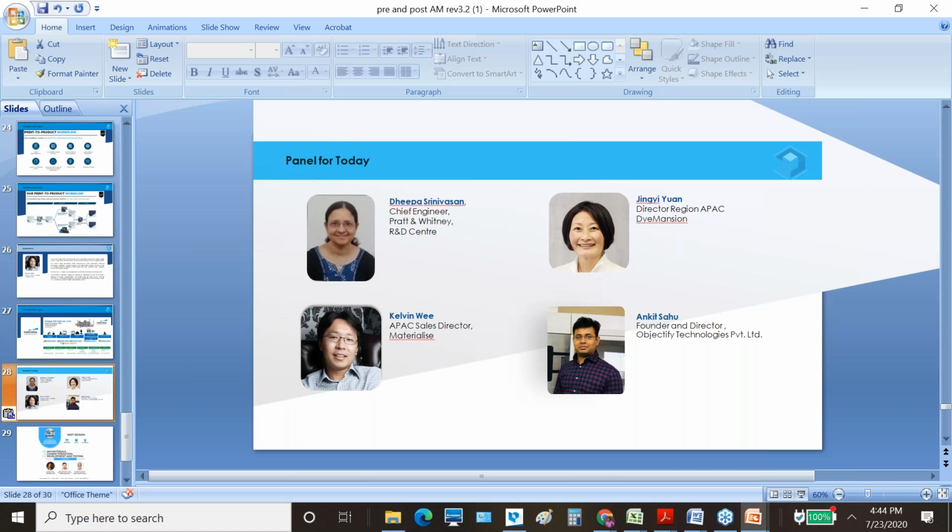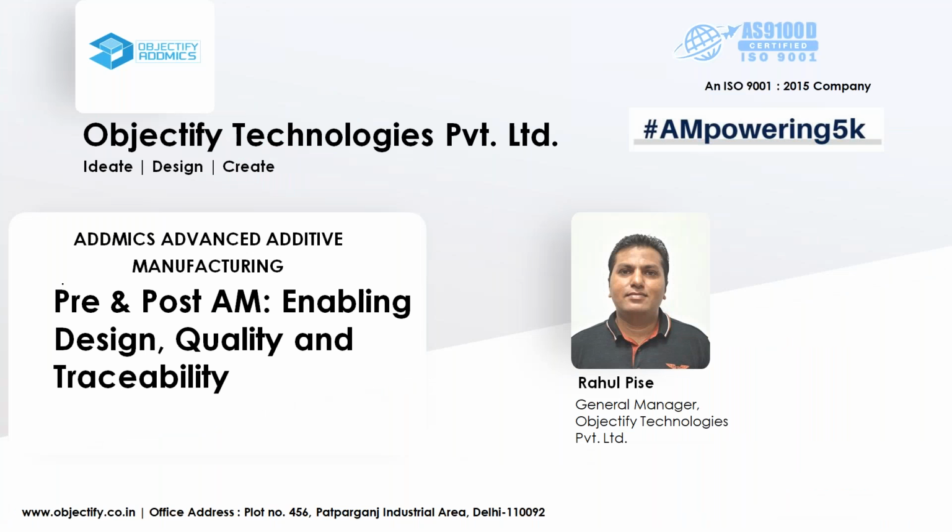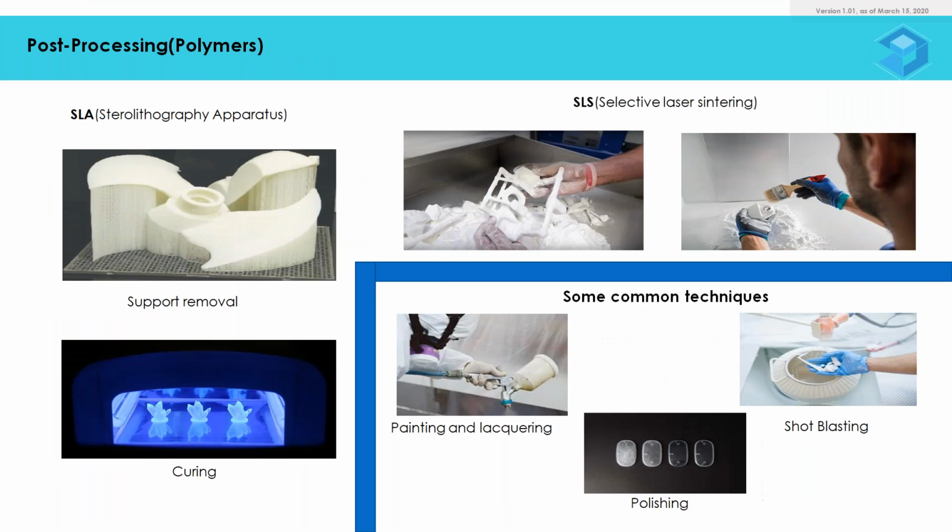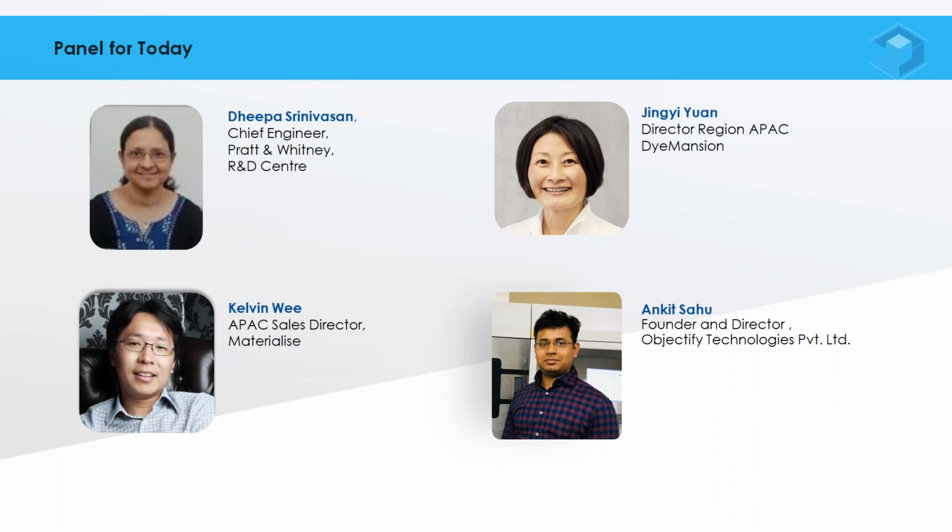And I'm not even talking about the raw material, which we're also afraid of. We have to use the same heat of powders, the same vendor of powders, the same machine, if you have to really look for a critical qualification. If it's a stationary part, if it is not greatly load bearing, all that is okay. And then whether to HIP, whether to hot isostatically press or not. Conventional wisdom in casting and other conventional manufacturing is you have to do a HIP process, especially for critical parts like in the turbines and in the space sector.